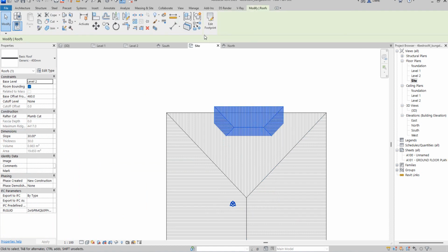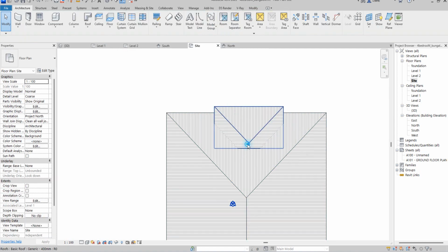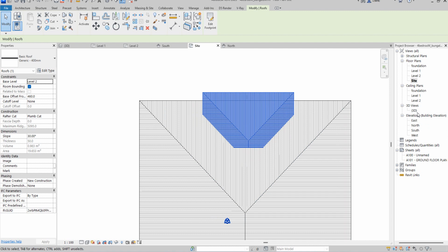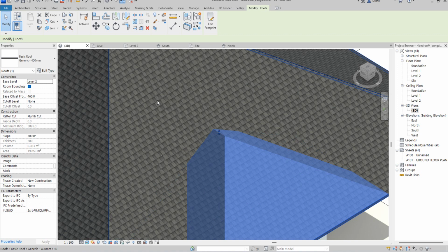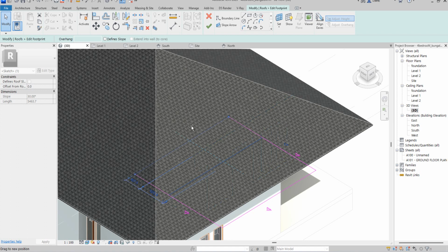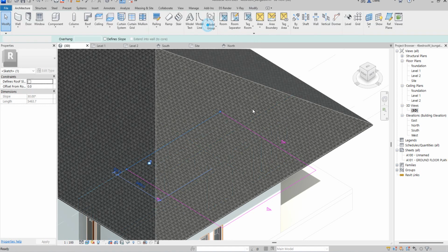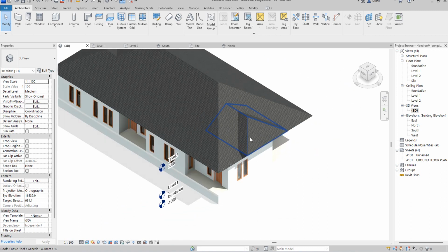What I need now is to click on this one and say edit. Now I'm going to toggle this so it defines for this line alone. I will say finish. Now I come to the default pattern. My problem now is that, let me get this from 3D, this roof is not entering into the other body of the roof. So I edit. From 3D you drag it a little bit inward, and you say finish. So this thing is done. It's already formed together. You can do that later by cutting it off. We're going to do that later, but not now. So we've gotten this one in place.